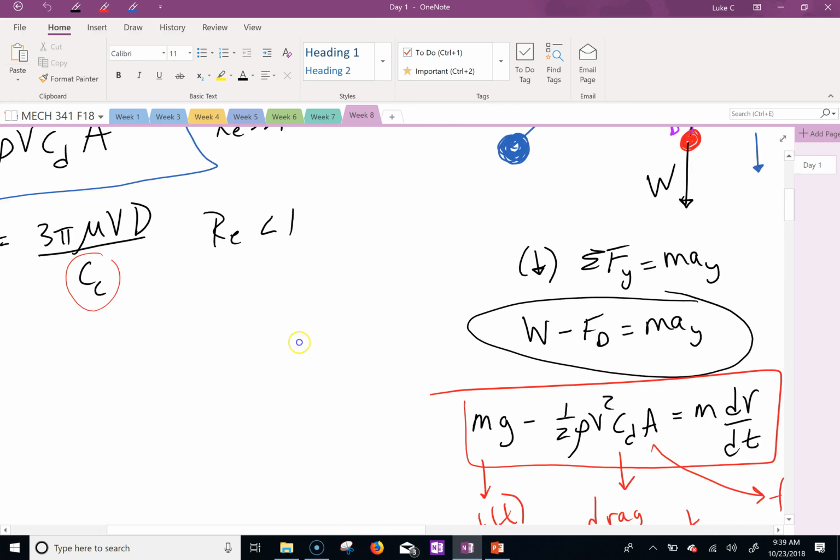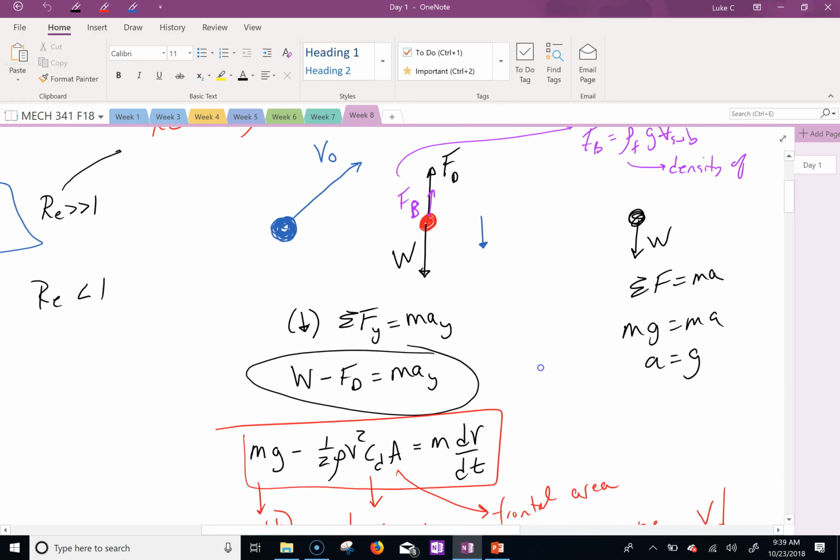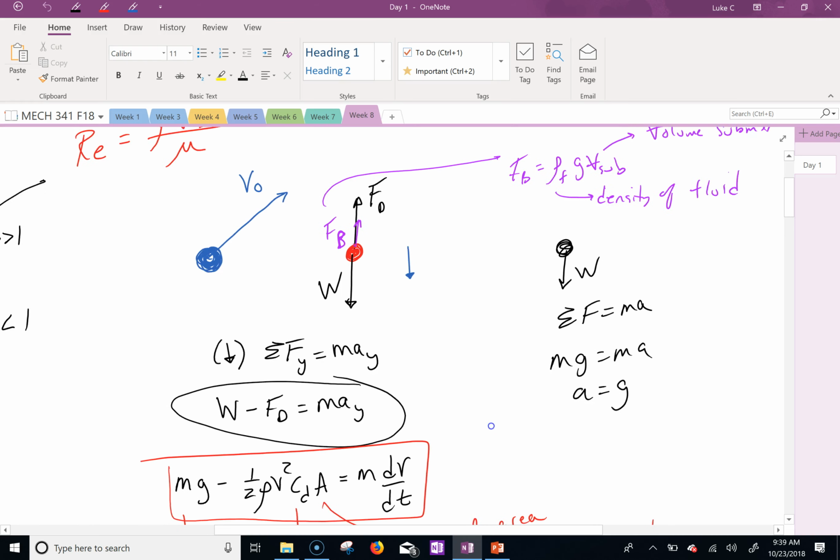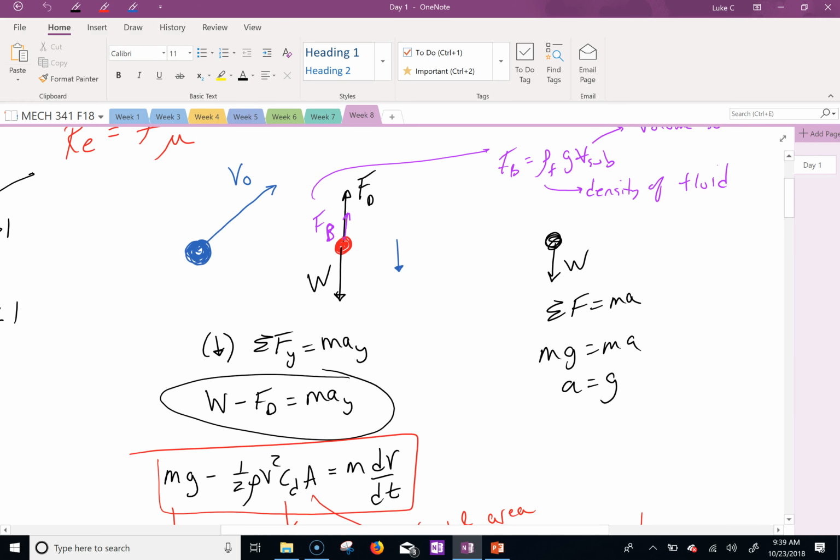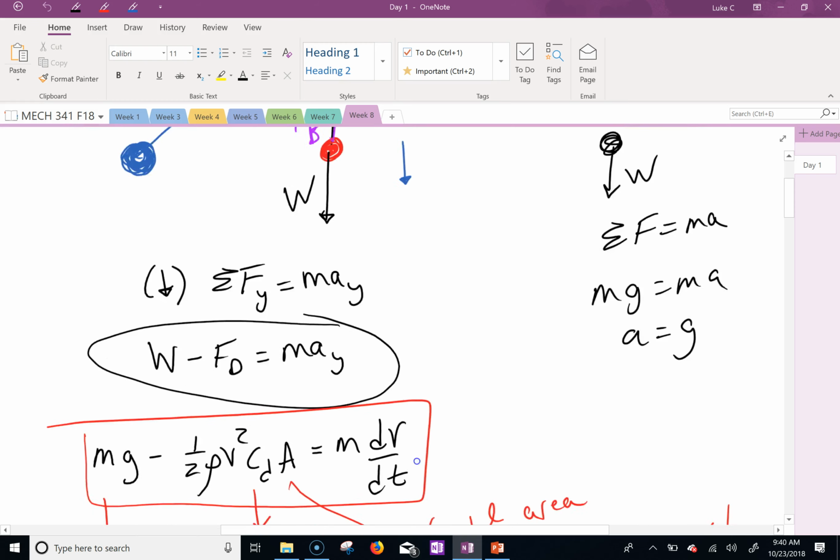So we talked about drag. We also talked about this stuff over here. We kind of did a side note, right? Which is good because it's still external drag. You have, say, any ball or any object falling in space. It's going straight down. We know that there's drag going in the opposite direction. We know there's weight force. We also know there's a buoyancy force, but we neglect that. Okay? So, in order to find